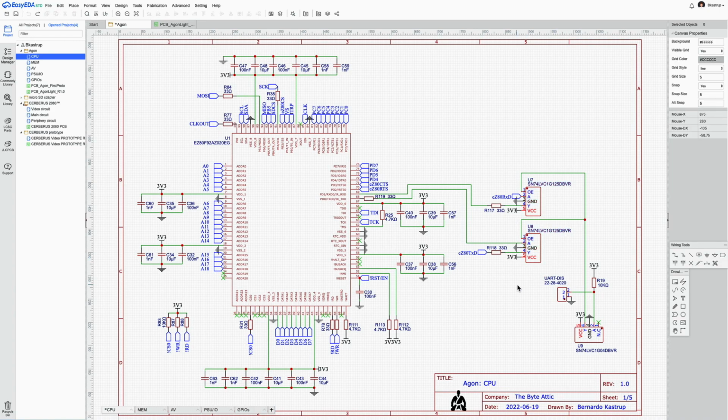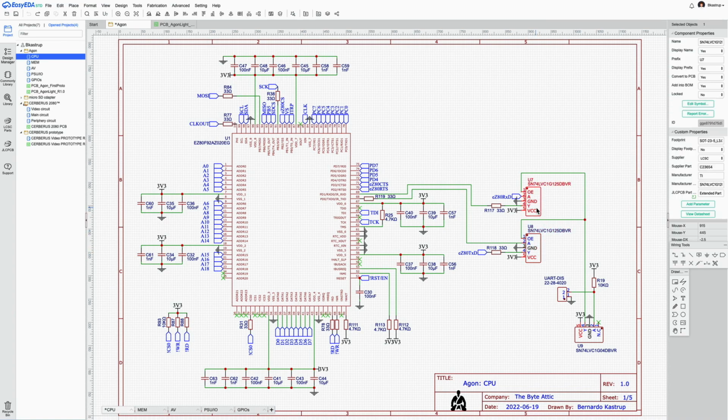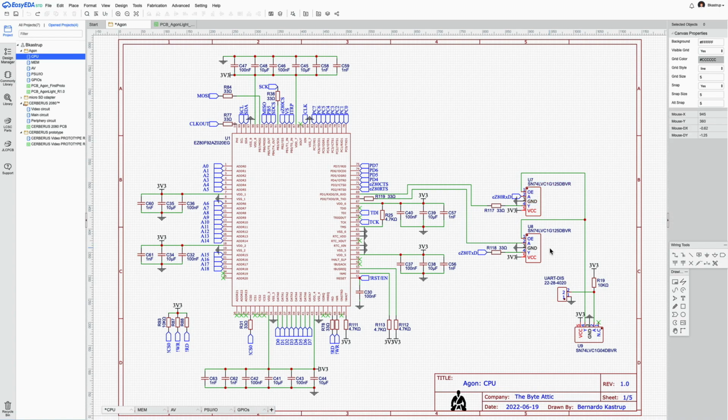The other reason is that these are basically buffers, so they strengthen the signal midway through their path. So it reduces amplitude loss of the signal because it's like repeaters, like Wi-Fi repeaters if you wish. Now I'm using the 33 ohm resistors on these lines as well. You see them here, and the purpose is the same. It's to absorb the high frequency reflections that cause ringing and reduce the amplitude of the ringing.